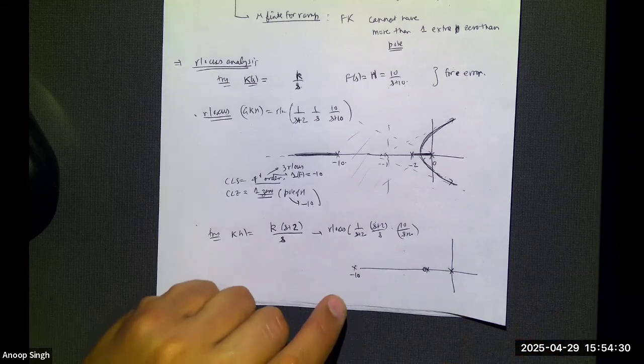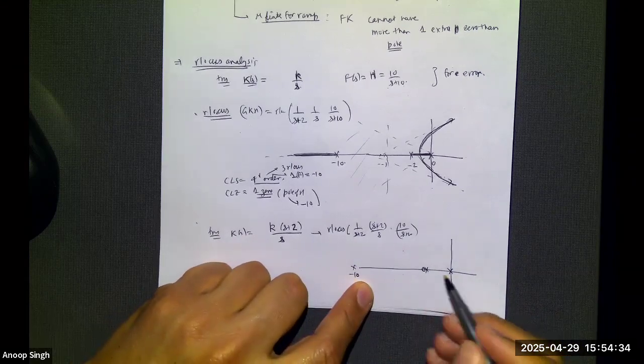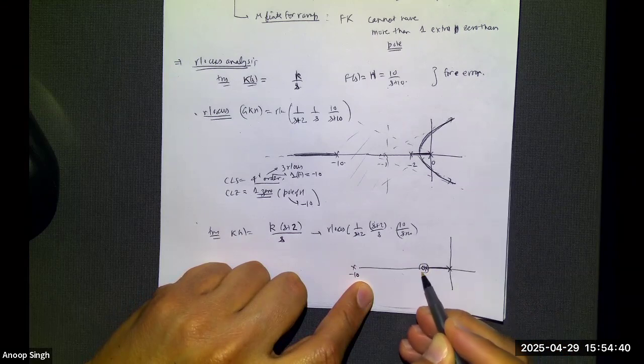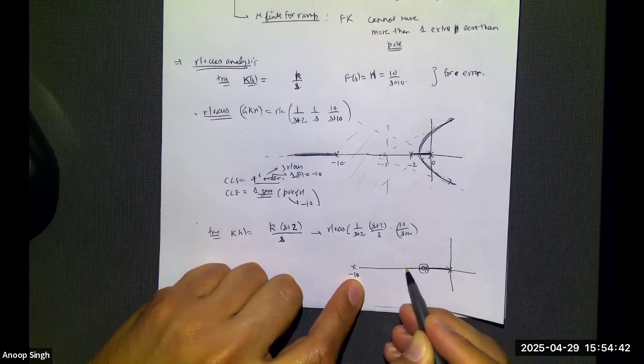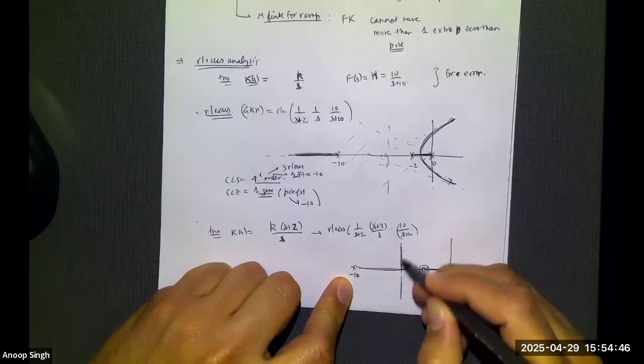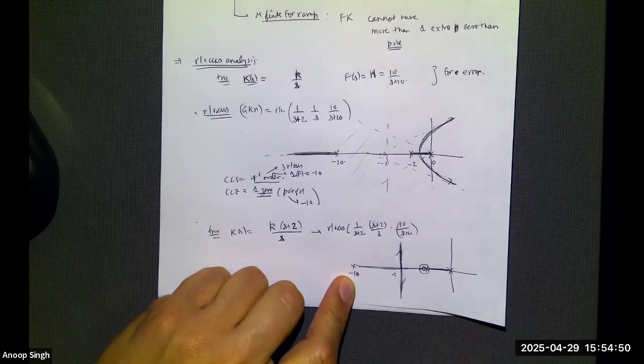So if you really draw the root locus, you will notice that actually, if you keep it very nice, detailed, then these two poles will come together over here. They'll do a small circle thingy. One will go to the 0, the other closed loop pole will go here. These two will come together and they will shoot up at -5.